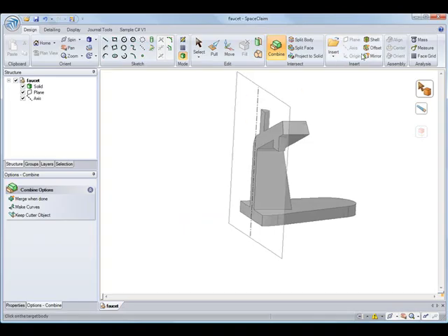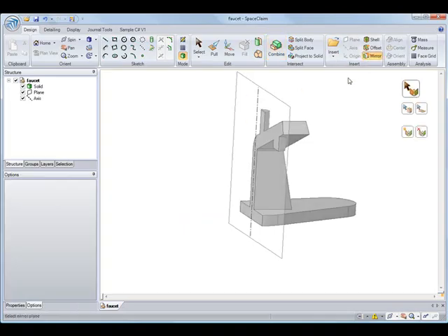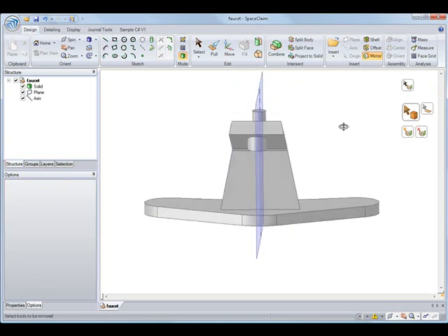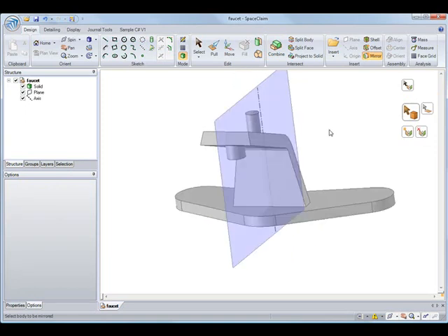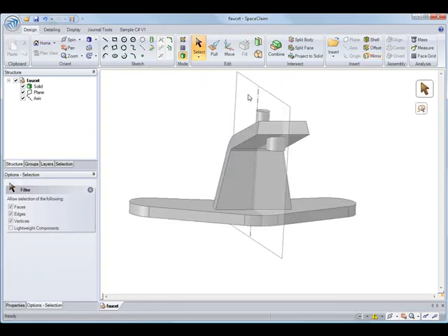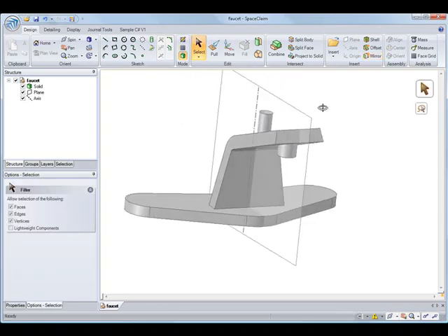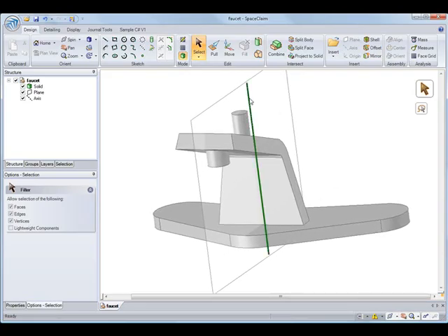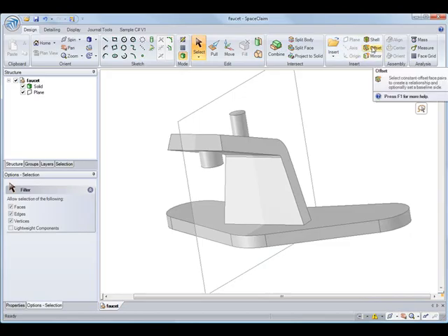So now I'll go back to mirror, and it starts you off by asking to name a face or a plane to mirror over. So I'll select our plane, and then click the solid button, and mirror the solid over to the other side. And you can see that the draft that I made on the spout is now mirrored to the other side. And actually, our entire part now has a mirror association. So if you make a change to one side, the other side will update.